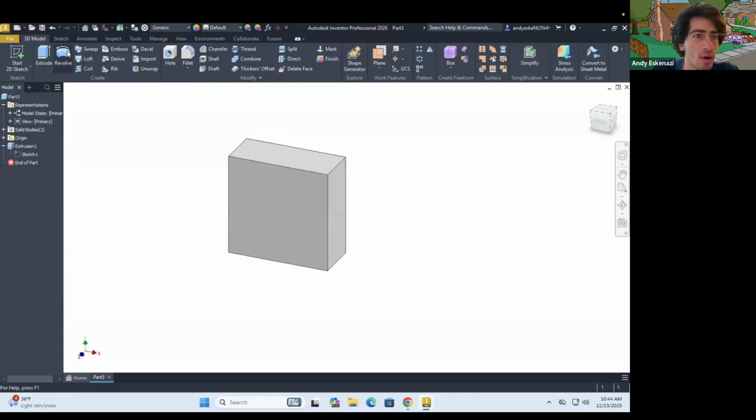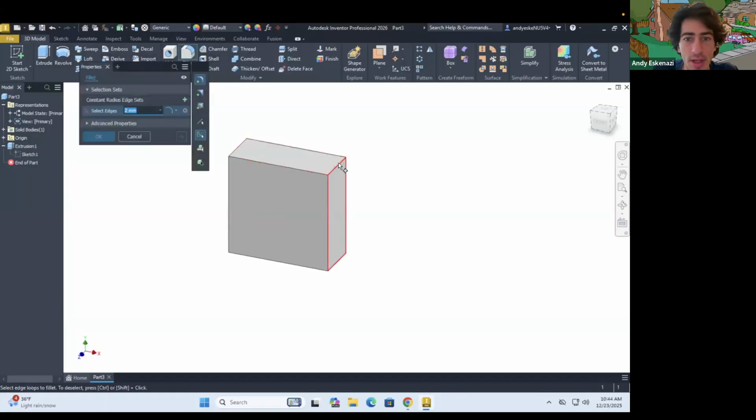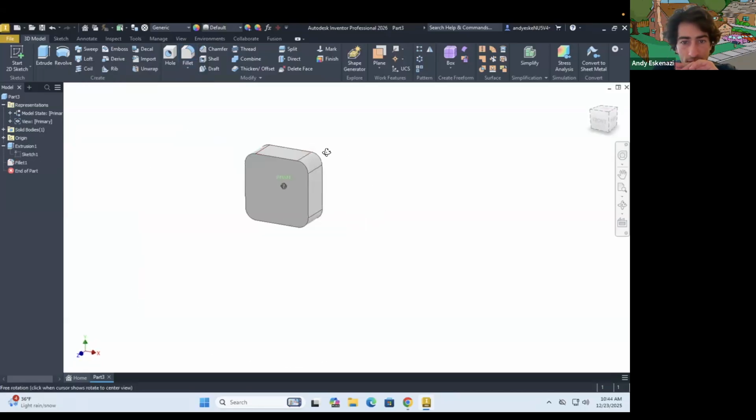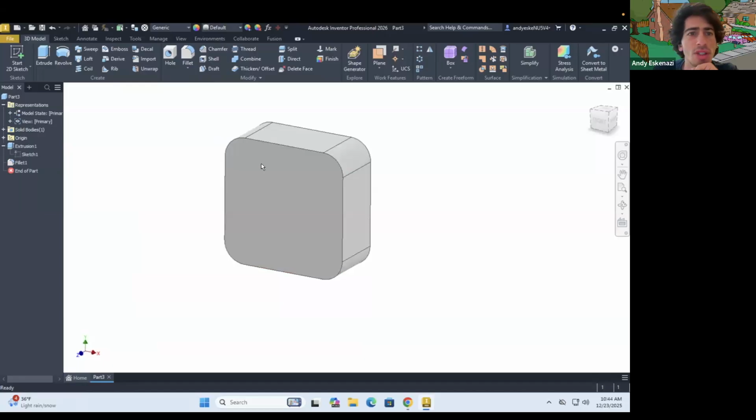So now we can go over to fillet. Then we can round. Actually, I want to select this option in there, like that single edge. So 1, 2, 3, 4. And we'll make that, let's say 50. What does that look like? Okay, I think that looks decent.